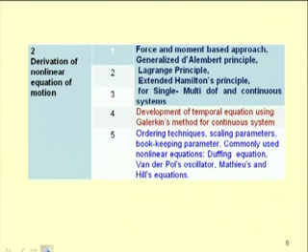In case of a continuous system, which contains a spatio-temporal equation, initially I will convert that to a set of temporal equations by using the Galerkin method, and then after deriving the governing equation of motion, we have to do the ordering using ordering techniques, and we may use some scaling parameter, bookkeeping parameter, and we will derive the governing equation of motion. Particularly we will be interested to find equations of motion of the type Duffing equation, Van der Pol oscillator and Mathieu type of equations. Besides that we may study many other different types of systems.